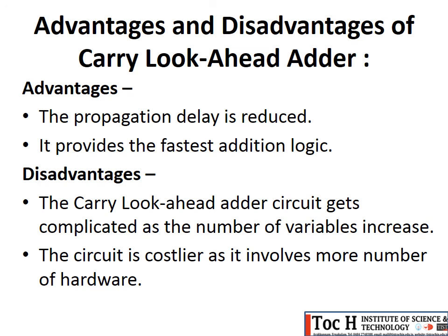So that's all regarding the adder design from module 6. With that we have covered the basic adder design concepts, that is static adder, dynamic adder, and carry bypass adder, another name for which is carry skip adder. Then we have seen the circuit optimization adder configuration, that is carry select adder, and we have seen two types of carry select adder, linear and square root carry select adder. And finally we have seen one major adder design, that is the carry look ahead adder.